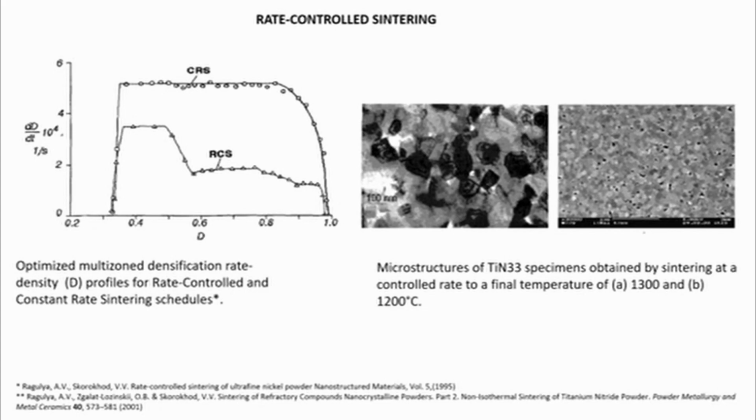One contemporary trend is unconventional sintering techniques. Connected to these, we just discussed two-step sintering, and the other is so-called rate-controlled sintering. We discussed this technique in my previous lectures, and now we show how to apply it to nanoceramic materials. This method of non-isothermal, non-linear sintering schedule has attracted the attention of ceramists due to its wide possibilities for structural control.